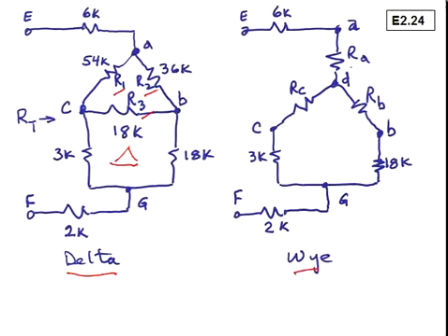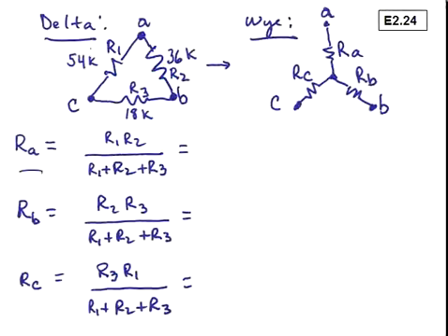On the Y side of the circuit, we've labeled RA, RB, and RC as the resistors that we'll have to calculate in a moment. We've developed another node in the circuit, node D, as a result of this delta to Y transformation. So let's proceed with establishing the values for the equivalent Y-connected resistors. Here we have again the R1, R2, R3 values in the delta circuit, and we want to determine the RA, RB, and RC. We had that node D in there.